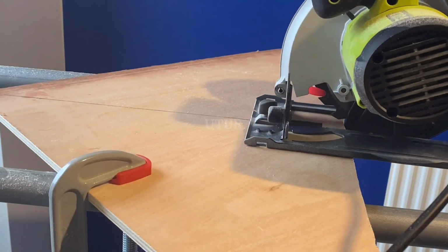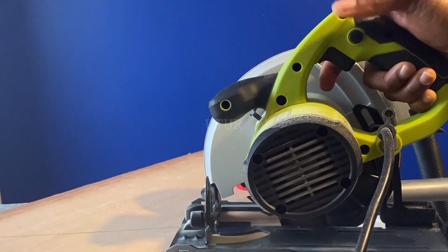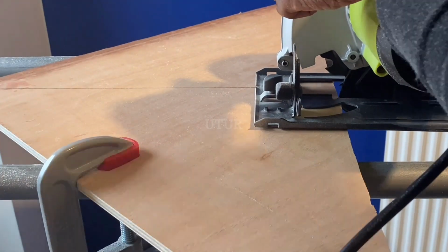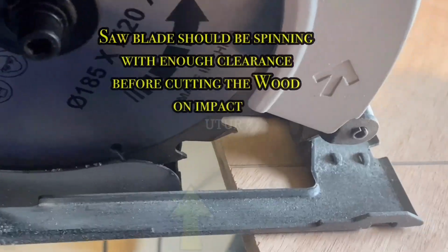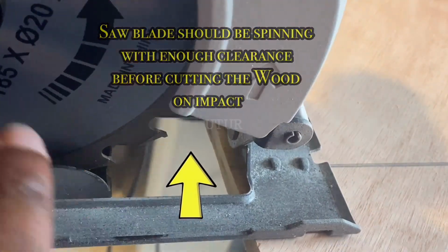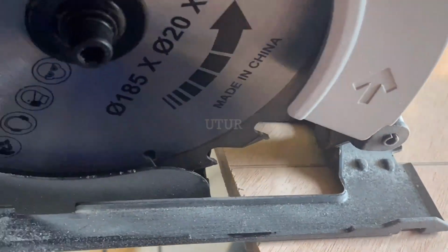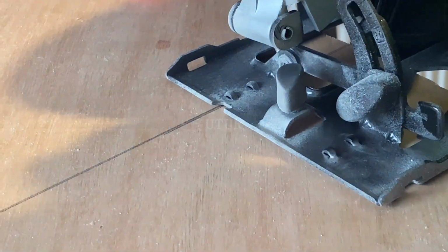And like I said previously, make good use of your safety lock-off button to prevent accidental starting. And when ready, press on the switch or the trigger. Make sure that the saw blade has enough room before it starts cutting through the wood.